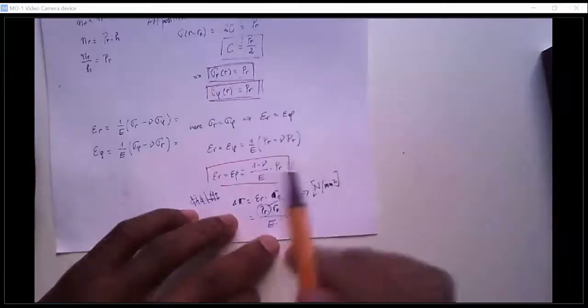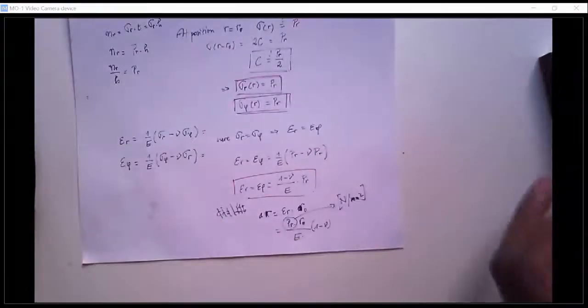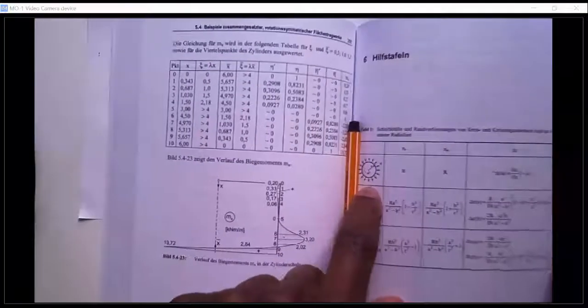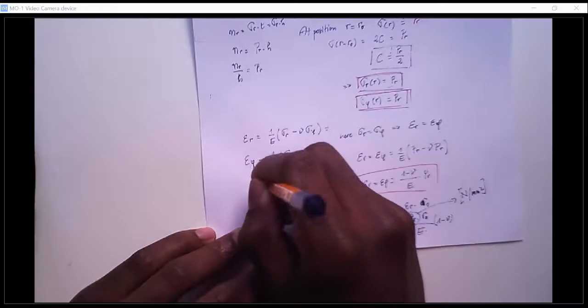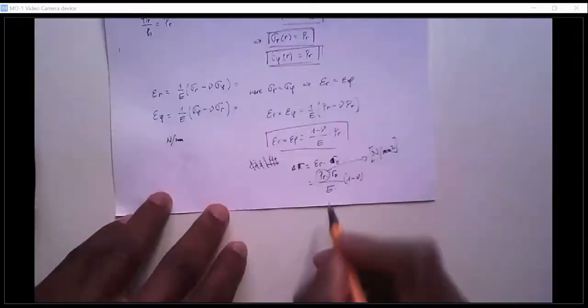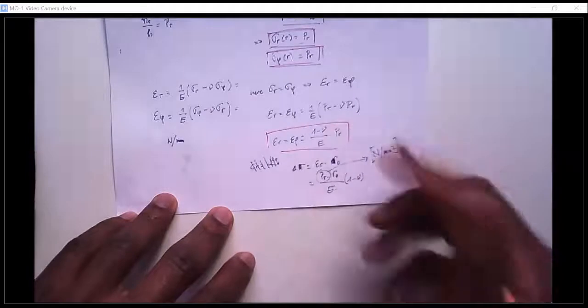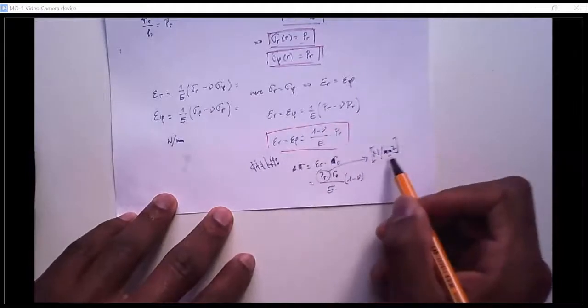But the stress they have in this book, they're working with line stresses, basically. So the unit the stress has over there is Newton per millimeter. But in this formula here, we actually need the actual stress with the unit Newton divided by millimeter square.